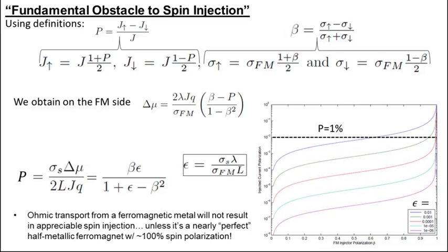However, the relevant materials properties are not forgiving in this respect. The ratio of conductivities between a semiconductor and a ferromagnetic metal is significantly below unity, even for highly doped semiconductors and highly disordered amorphous ferromagnetic metals. Likewise, the ratio of length scales is small due to the fast spin relaxation in the ferromagnet, leading to a spin diffusion length, lambda, of approximately 10 nanometers, whereas in semiconductors with low spin orbit interaction, such as silicon, transport lengths can be 10 microns or longer, even at elevated ambient temperatures.